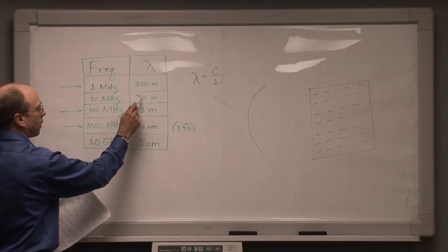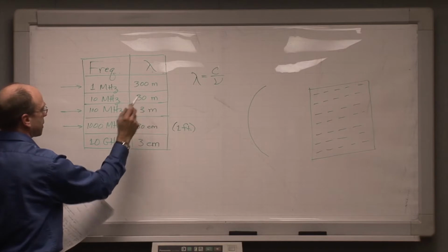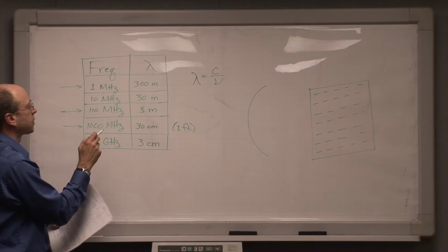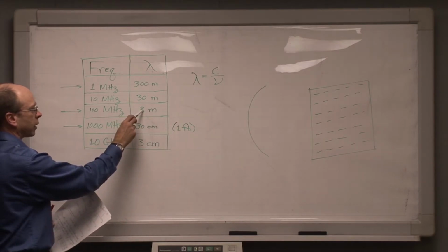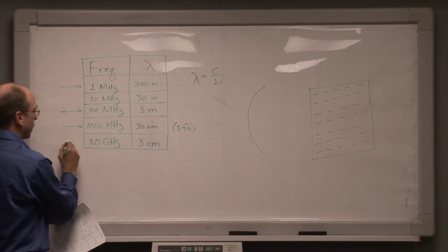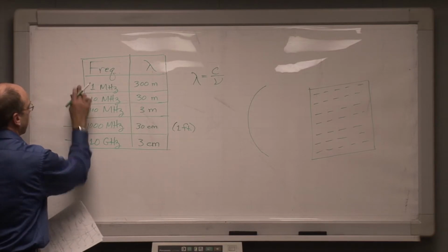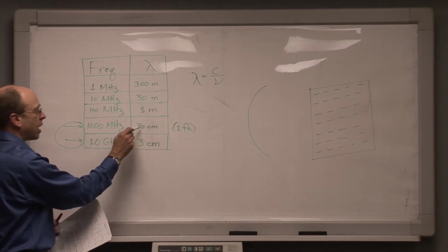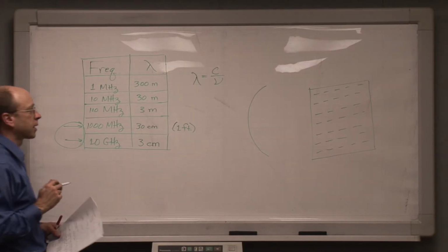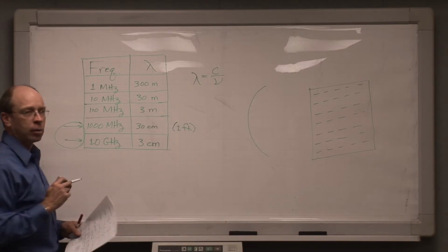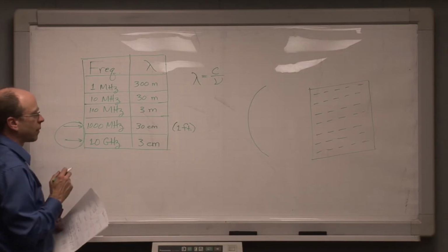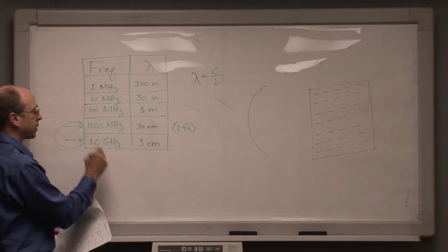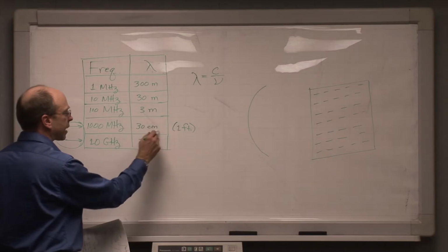Airplane antennas that go inside airplanes aren't going to be 30 meters in size. Even 3 meters in size is a push, although Navy AWACS planes work with radars at about 400 megahertz. But more practically, these are the wavelengths where we can build fairly compact antennas that are well adapted for fitting inside aircraft, spacecraft, small boats, small vessels. And aside from propagation characteristics, that's why these frequencies from 1,000 megahertz upward to 10 gigahertz and above are considered highly desirable for radar systems.